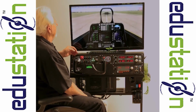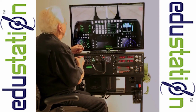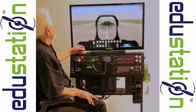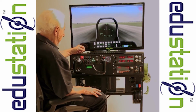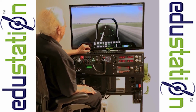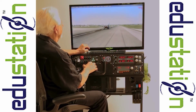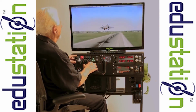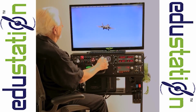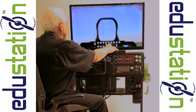So what we're going to do now is we're going to take off at about 120 knots. So I'm going to go to full power and we'll accelerate quite quickly. And so now we're just passing 100. 150, and I'm going to go to the outside view and just gently rotate the plane up. You'll see our landing gear is down, so I'm going to slide the horizontal switch on the right side of the yoke. That's going to bring the gear up, and I'm going to return to the cockpit view and zoom out.